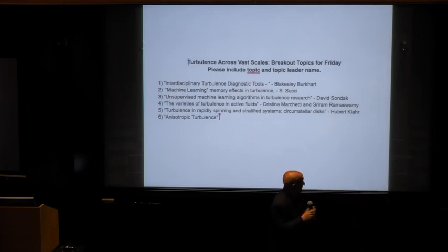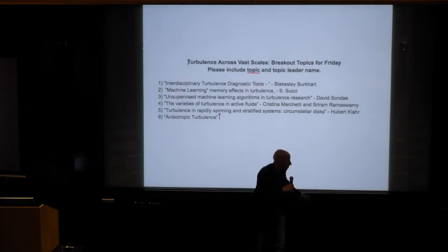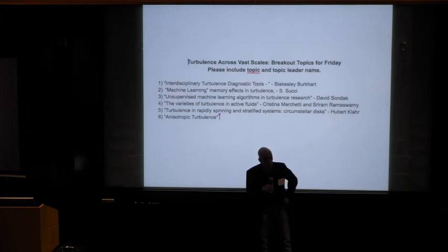Maybe I can just make one technical comment on the Reynolds number. When you're going to low Reynolds number, that's actually a regular perturbation from zero, so to speak. And so you can do an asymptotics where you expand around Reynolds number equal to zero in powers of Reynolds number, as long as you're in a finite system size. And so you don't have this problem like at high Reynolds number where you take Reynolds number off to infinity. Right, and that's singular. And you can't pretend as though you just got rid of viscosity altogether because it's still producing things, shear flows off of boundaries and things like that.